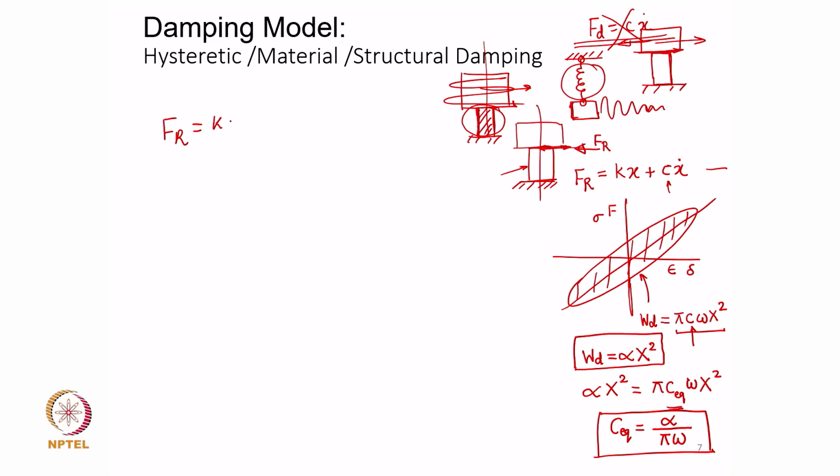Now, this x I will write assuming again a harmonic response or harmonic motion of the mass, which we can write as either x sin theta or x sin omega t, or you can as well use a complex expression for x of t. So, capital X e to the power j omega t is similar to writing x cos omega t minus phi.